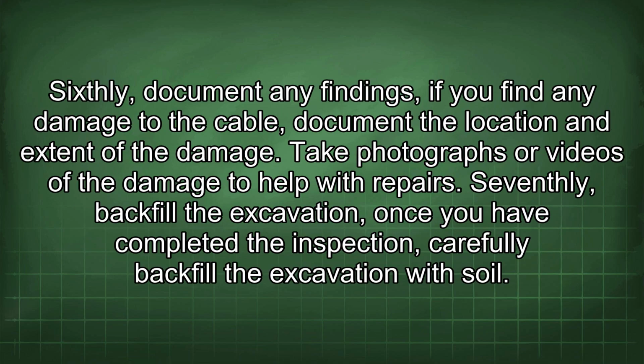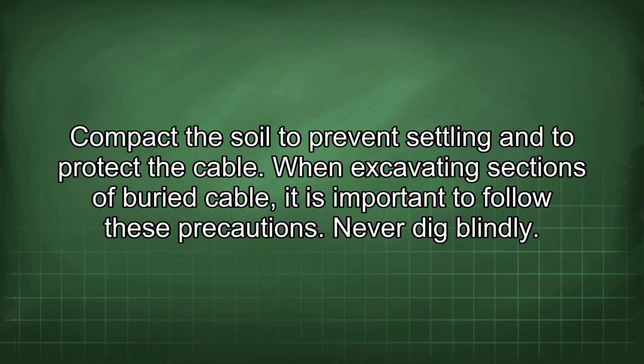Sixthly, document any findings. If you find any damage to the cable, document the location and extent of the damage. Take photographs or videos of the damage to help with repairs. Seventhly, backfill the excavation. Once you have completed the inspection, carefully backfill the excavation with soil. Compact the soil to prevent settling and to protect the cable.